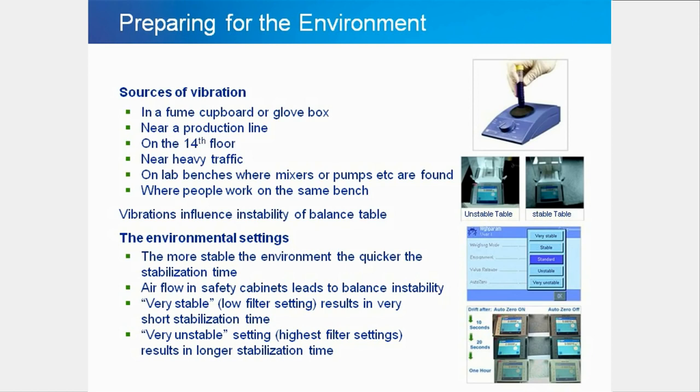The airflow in safety cabinets leads to balance instability, but can be compensated for by the filter settings. Very stable is a low filter setting and is suitable for the lowest of vibrations. Stabilization time is very short. Very unstable is the highest filter settings for relatively high vibration environments and will result in longer stabilization times.